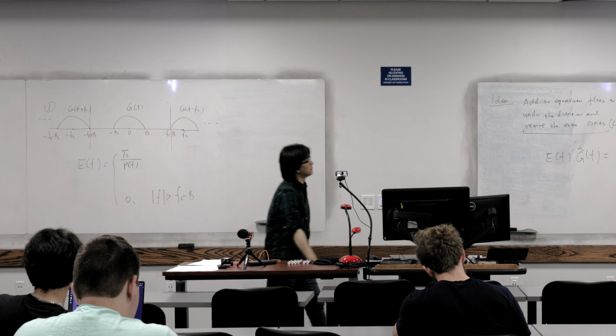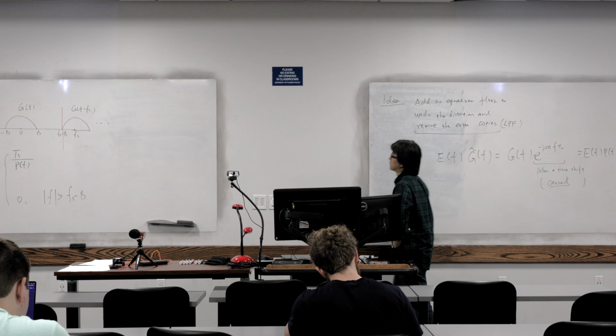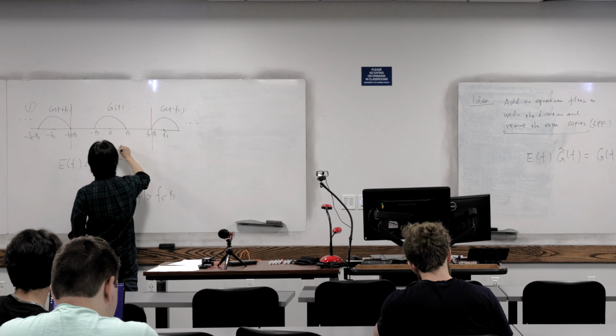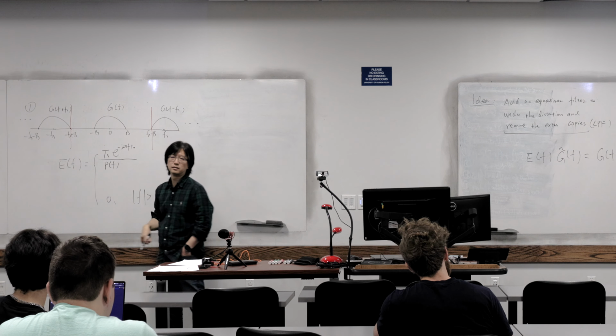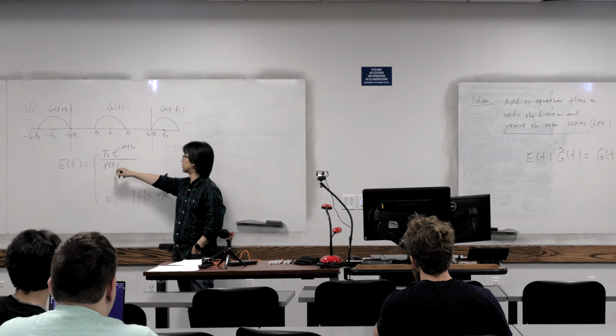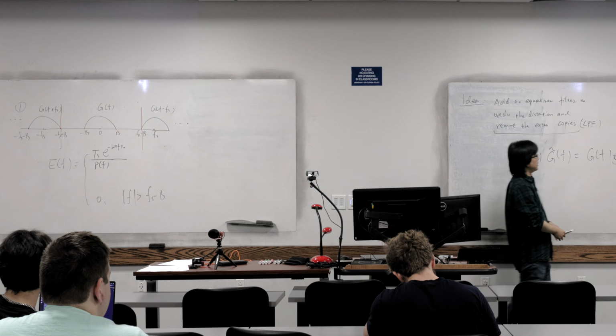And then, don't forget the time shift, so we just write the time shift here, e to the minus j 2 pi f t0. That's it. We just divide out the impact of P(f), and the P(f) multiplied here will be gone. We don't have P(f) anymore, so very simple.